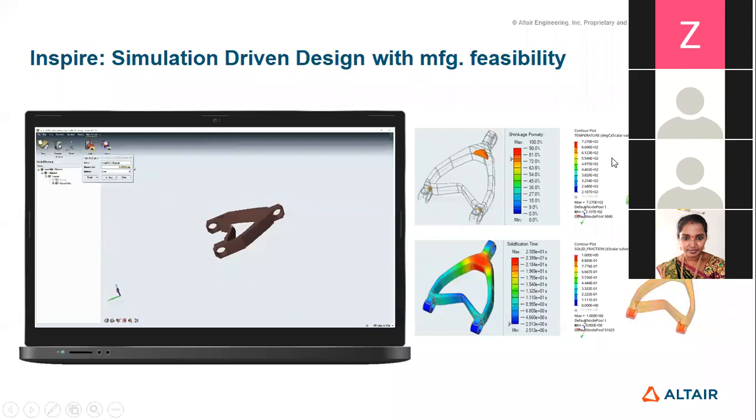you can directly simulate the component and get the output about what your shrinkage would be and where the shrinkage porosity would be. In the casting process, where your component thickness is very high, it will take more time to solidify at that location. If that thick region solidifies last, there would be some tendency to get shrinkage porosity. So it is also showing the shrinkage porosity tendency. Basically it is the feasibility check after the optimizing.